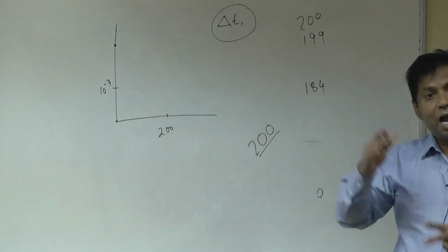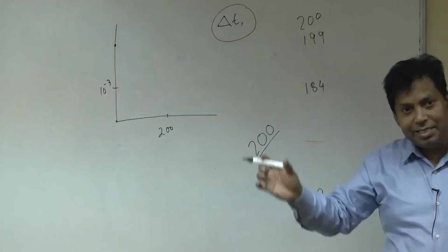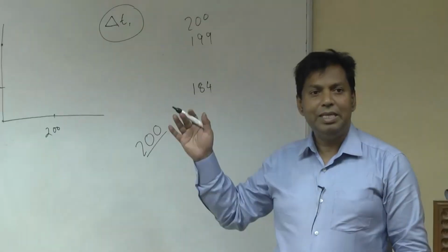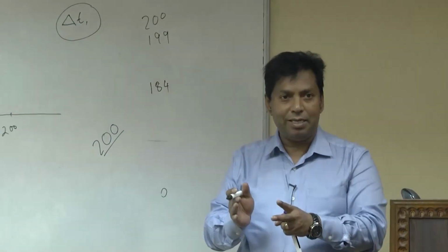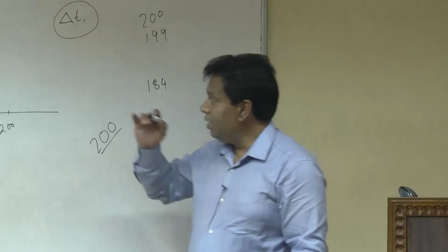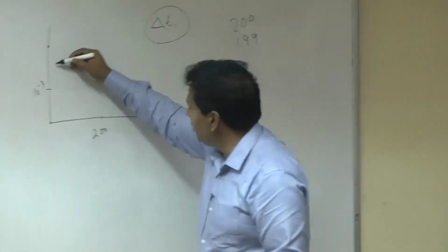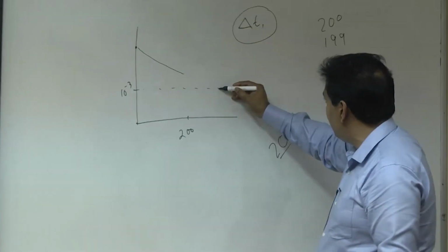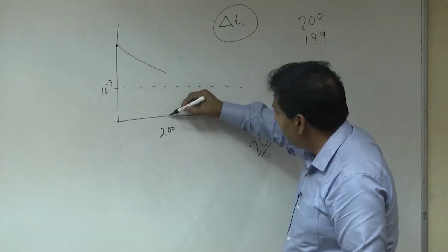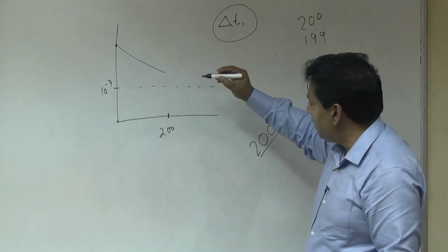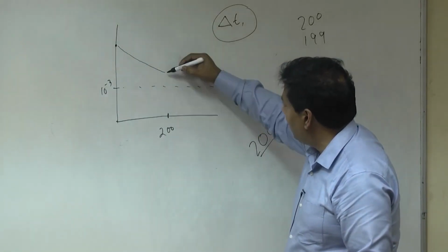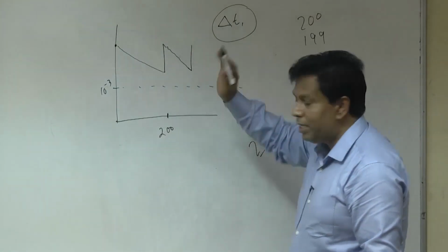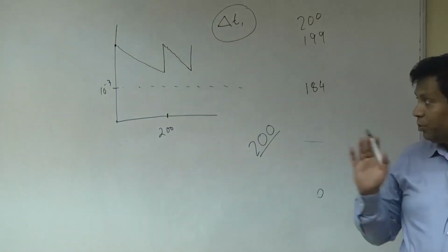3000. So that is the outer iteration, 3000. And in each time step we have about 20 or 25 iterations. That is called inner iteration. So two iterations. You have to be very careful, because sometimes it is coming here and not coming down to here. That should be the convergence line. It's coming here, but you told it the maximum iteration is 200, and it does not come down, then it goes back up there and comes here again. It means it's not actually converged. So you have to check this.